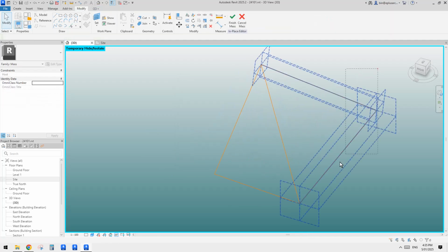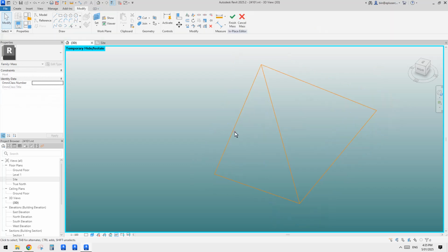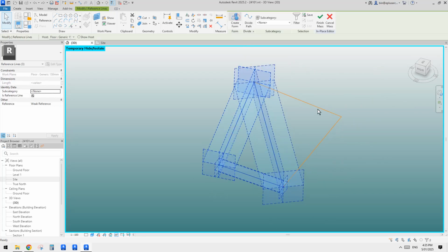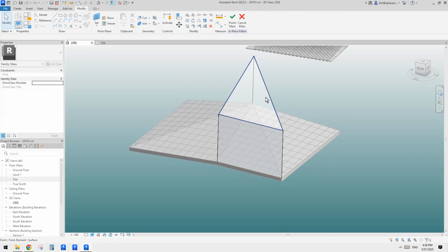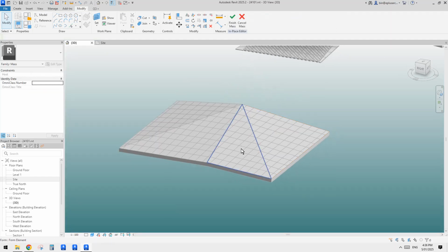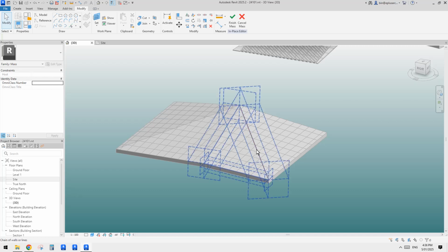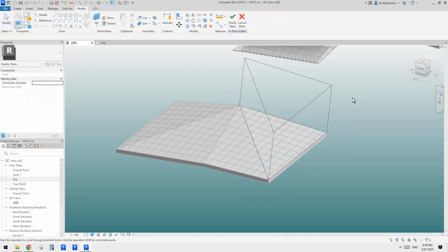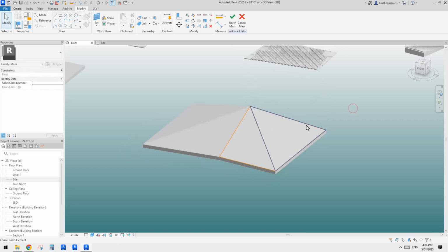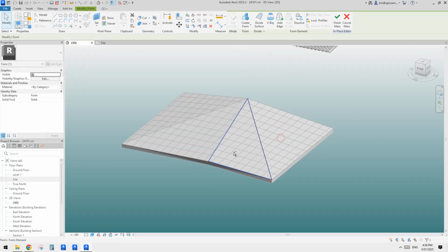So now I'll select this. Maybe select these 3, create a form, and type HR, and then let's delete this top so we still have that surface there. And again, Tab, Control Select, and then create another one. Press the keyboard up to switch between different options. Now we have these two surfaces, right?